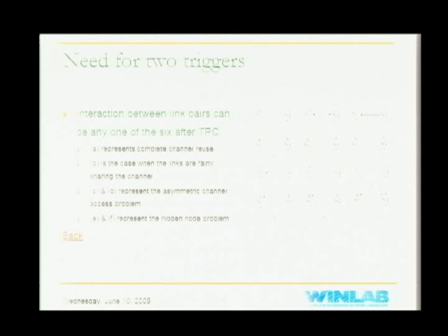Because when they both transmit, they have interference, right? Your SINR is about 0 dB. And if only one of them transmits, the transmission would be better and more reliable if you use more power. So here basically AP A and AP A's client are very close, AP B and AP B's client are very close, but AP A and AP B are far enough apart.